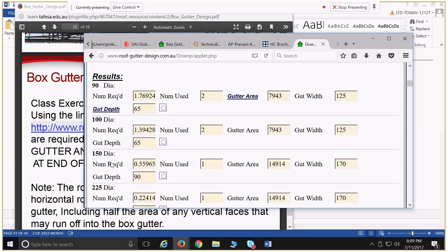Well, yes, it is. Certainly, it is added risk. That's for sure. Because with that scenario, you've got a downpipe at either end, and you have your high point here, and you have slope heading that way, slope heading that way. And that scenario is much better if you've got soil movement as well, because if you've got uplift happening.